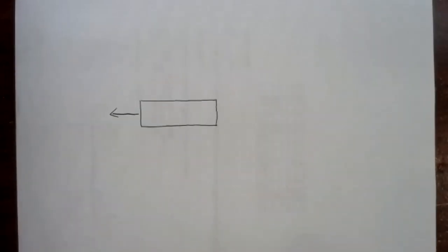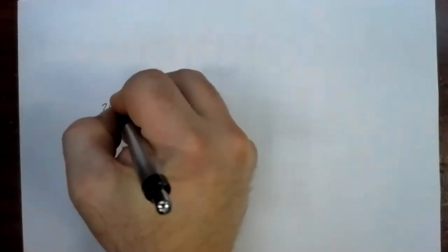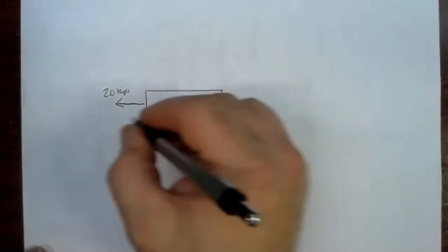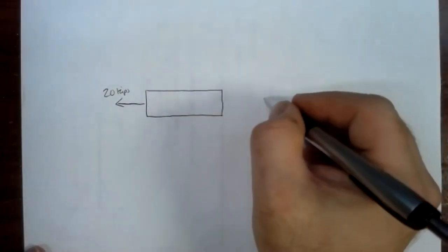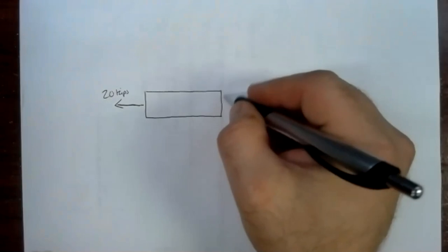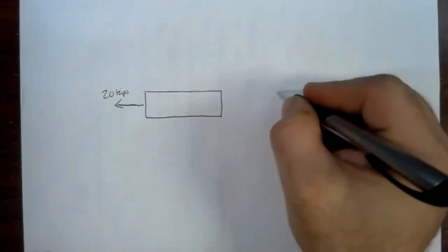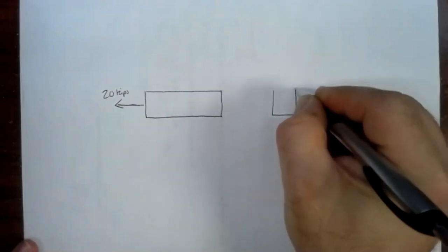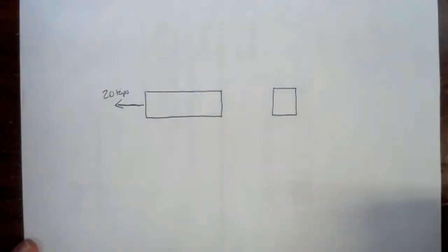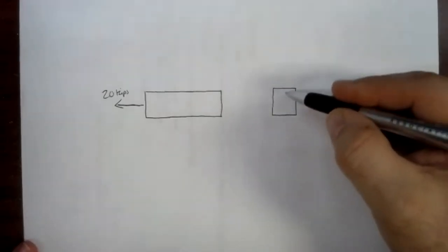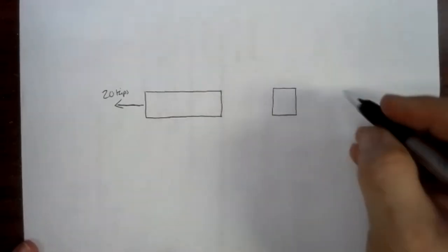Yeah, there we go. So here's this member that we've just cut through. We've got 20 kips of force there. When you cut through one of these, you're not thinking about it anymore as just a single line that is infinitesimally small. It's got some area to it. If I were to cut through this and view the end I cut, here I'll draw an end view. It's going to be some rectangular shape. So let's say this is maybe a piece of wood or something like that, like a 4x4 or something. We've got a rectangular cross section.